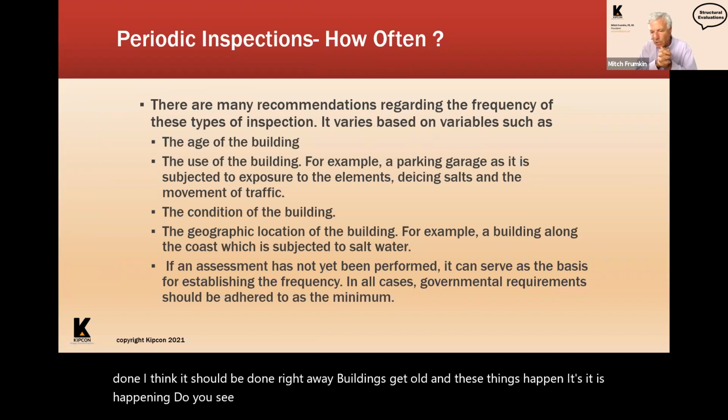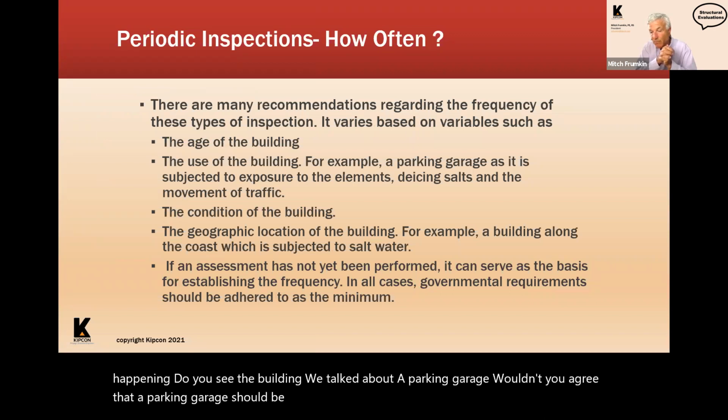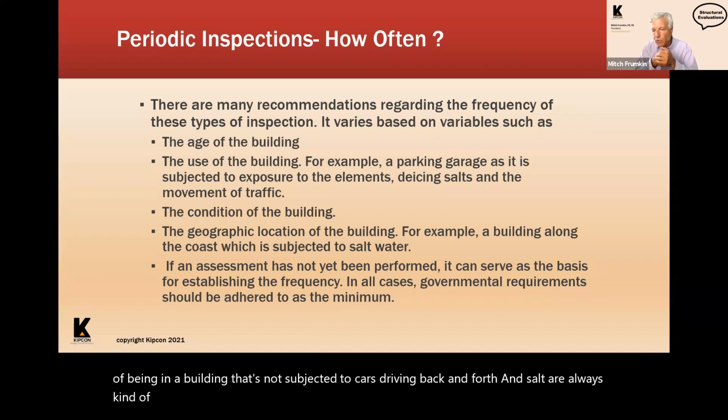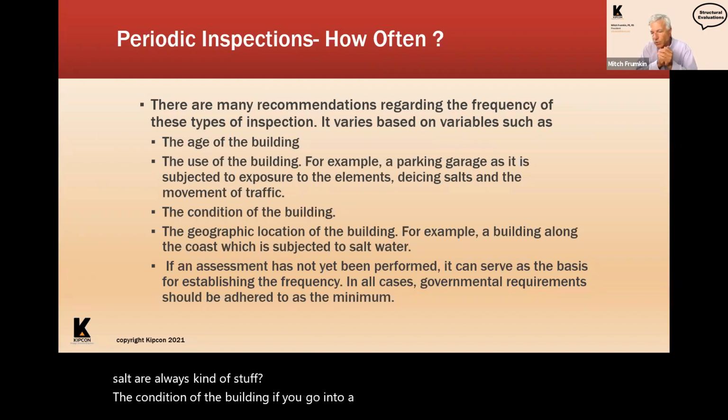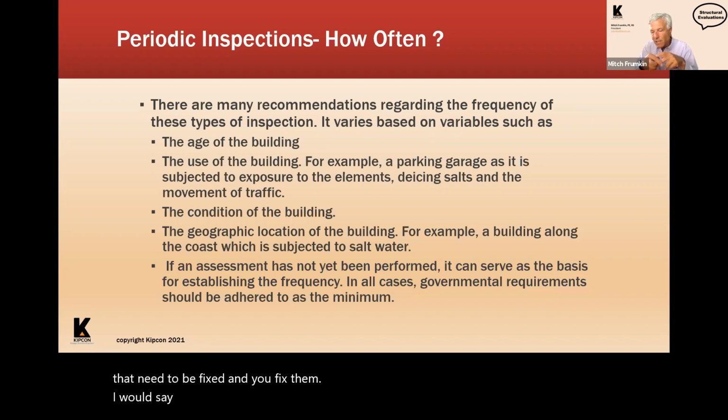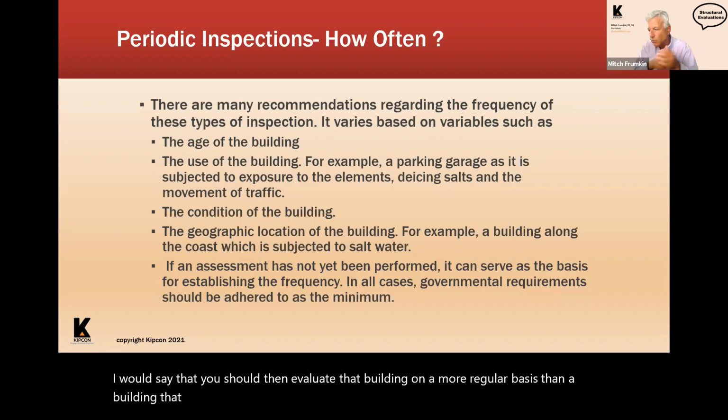We talked about a parking garage. Wouldn't you agree that a parking garage should be inspected sooner and more frequently than a column and a beam in a building that's not subjected to cars driving back and forth and salt and all this kind of stuff? The condition of the building. If you go into a building and it's older and you see some things that need to be fixed and you fix them, I would say that you should then evaluate that building on a more regular basis than a building that is brand new.